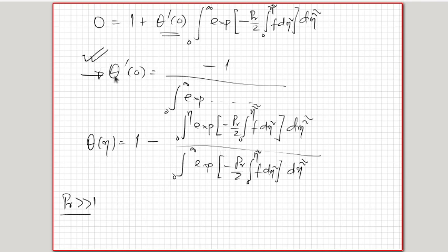Okay, so from both of these, just substitute for this f. Prandtl number much greater than 1, f is equal to 0.332 into eta squared by 2, and Prandtl number much less than 1, we substitute f is equal to eta in this integral and simplify.